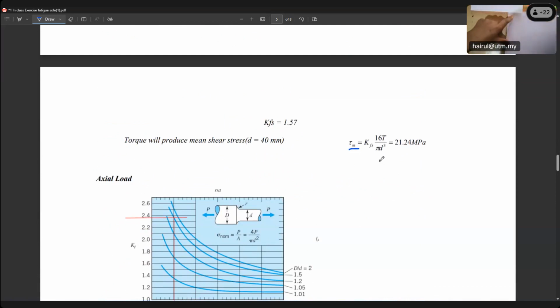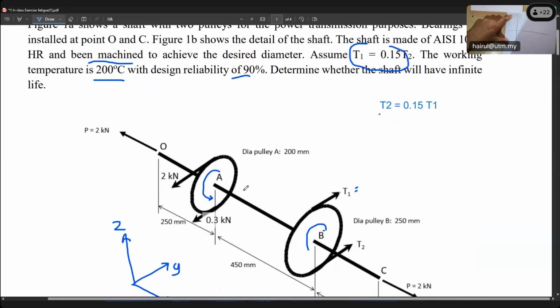Because for torsional stress along the shaft, if you look, the shaft is rotating. We have torsional stress at the shoulder after A, along the circumference of the shaft of smaller diameter D40, and it remains. If you look at my live video, torsional stress versus time is straight. Right, class? Because torsional stress is along the circumference, whatever the rotation, it remains constant. It's not fluctuating. Straight. So torsion only has mean. There is no alternating component, it is 0.